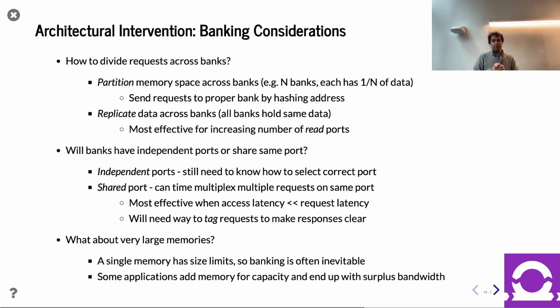To the point that brought me to change the slide, the original question: how independent are these ports? Are they independent ports? Are they shared ports? There are trade-offs there. And it's one of these things where design for this memory isn't completely in isolation. It's often done in conjunction with surrounding context and knowing how to interface with it. If you have long latency requests, perhaps all these banks can go through the same port. If you really have low latency requests and just tons of requests, then perhaps each bank needs to have its own port, for example.